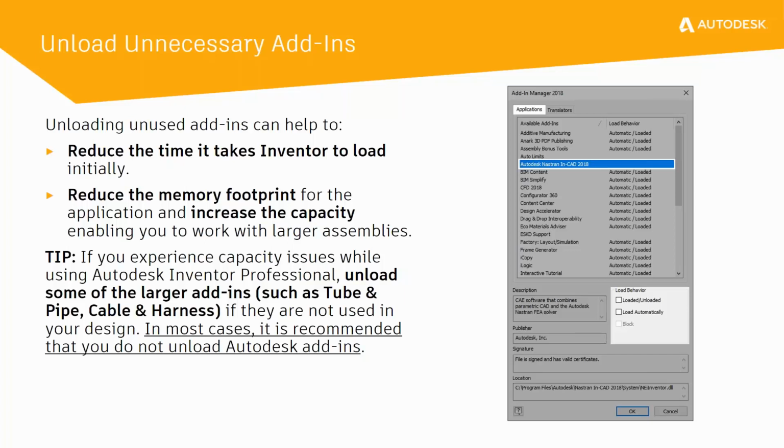Maybe you don't use Frame Generator. Maybe you're not interested in Materials Advisor. There's a whole bunch of functionality in there that, if you are hitting a limit in your system to be able to work with large assemblies, then potentially you could capture back some of your system resources by unloading and turning off the automatic loading of add-ins inside of Inventor.